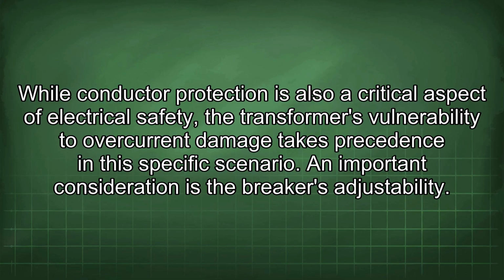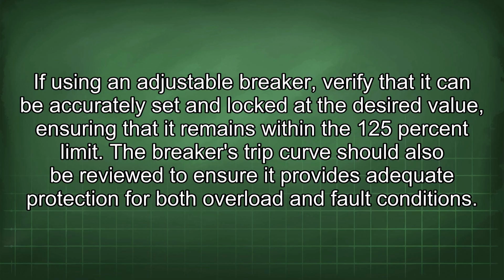An important consideration is the breaker's adjustability. If using an adjustable breaker, verify that it can be accurately set and locked at the desired value, ensuring that it remains within the 125% limit. The breaker's trip curve should also be reviewed to ensure it provides adequate protection for both overload and fault conditions.